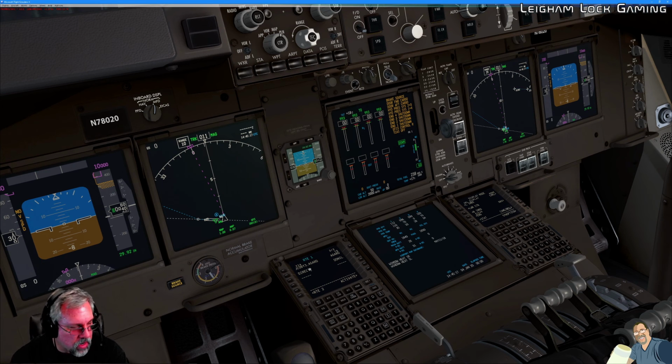And then when we do have a via route, we put that in first. And then our waypoint. And we just continue this process for the remainder of the indicated waypoints and via routes in our flight plan.